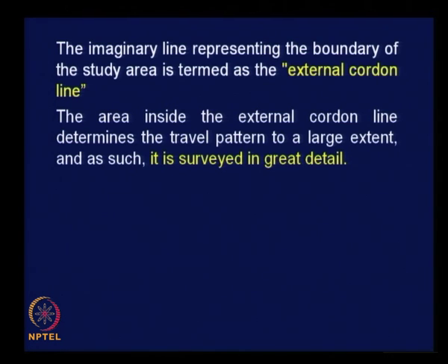The area inside the external cordon line determines the travel pattern to a large extent, and as such it is surveyed in great detail. Once you fix a boundary, do detailed surveys within the boundary, okay, covering the whole of the area.